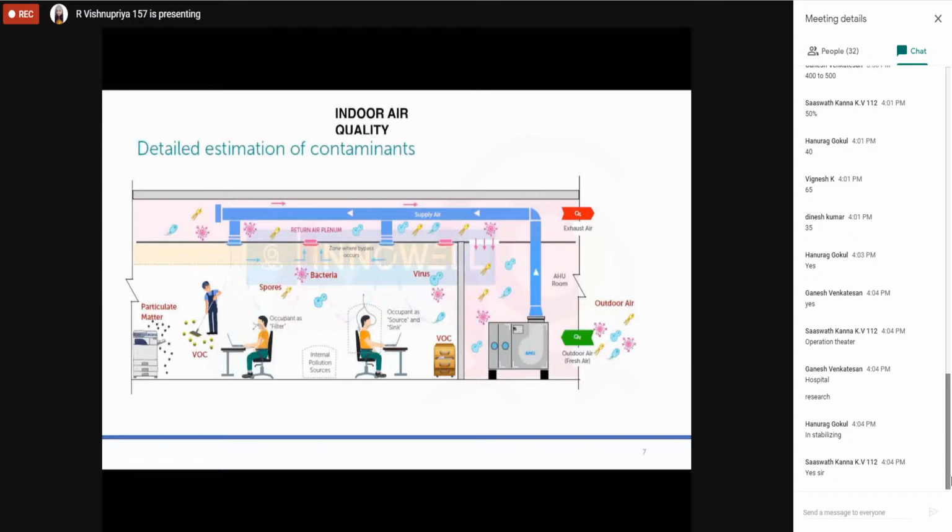It is a 1 lakh class, but in a clean room we have 1 lakh class, 1,000 class, 10,000 class, like this. We have different classes. So 10,000 class will be chosen for a tablet manufacturer or something like that, but there are different specifications given by different manufacturers. Just imagine if you take 1 volume, only 1,000 or 10,000 particles will be there, but still they will be there. You cannot remove 100%, but we have to give that information. We have to live with that condition.